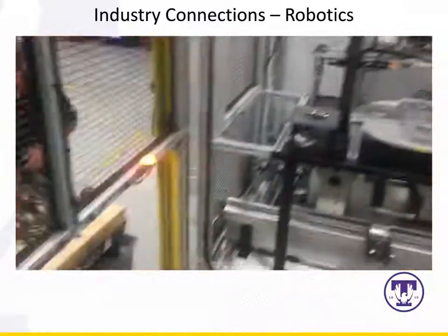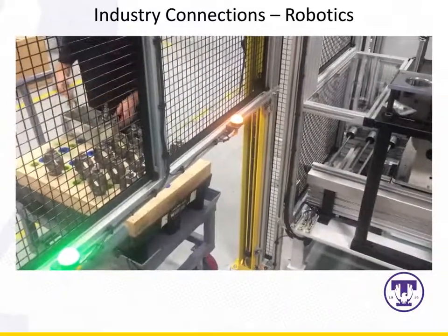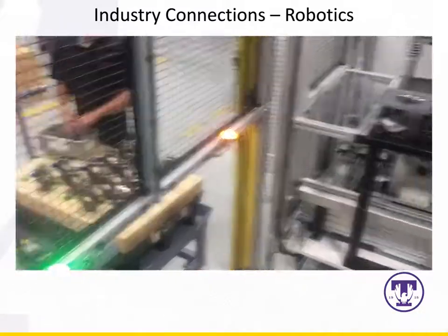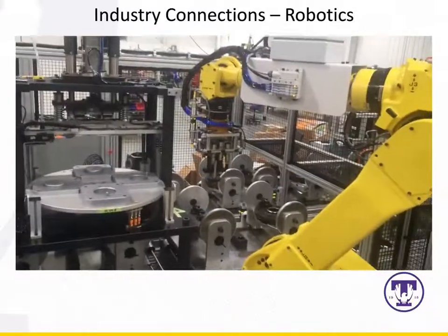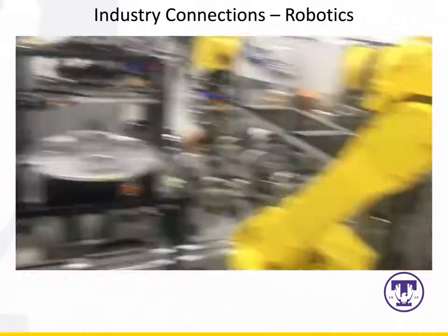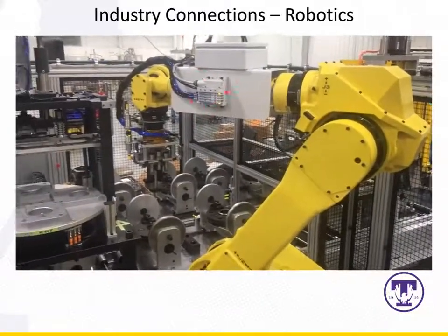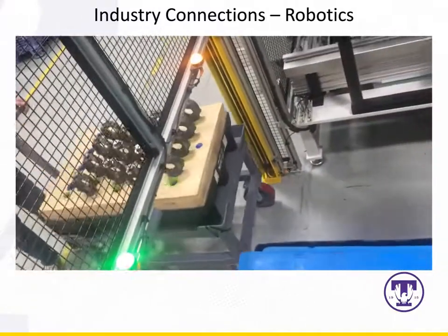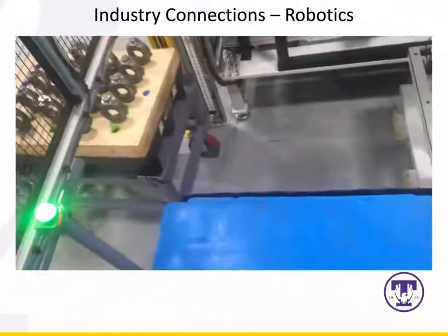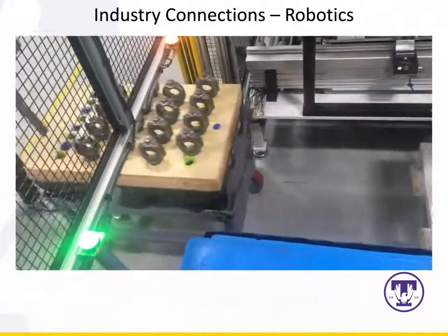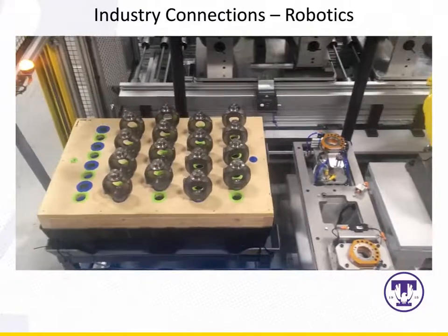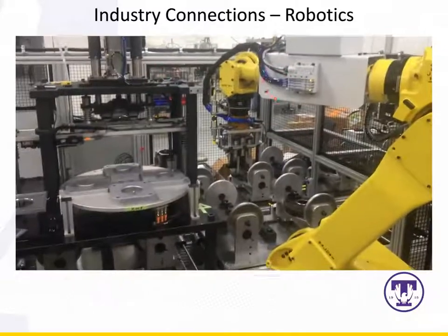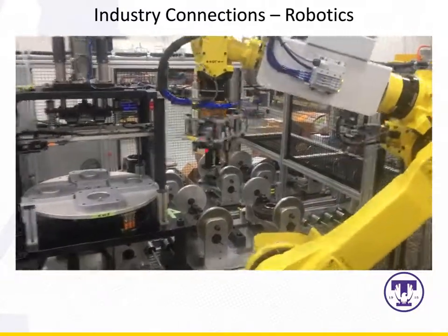So first, this is the interior of the robot cell, and I am perched above. Here we see a valve manifold on the side of the robot arm that is going to control the motions at the end effector. That's how we refer to the manipulator of the robot, the thing that actually interacts with the different pieces. So that valve manifold here is used to control this end effector.